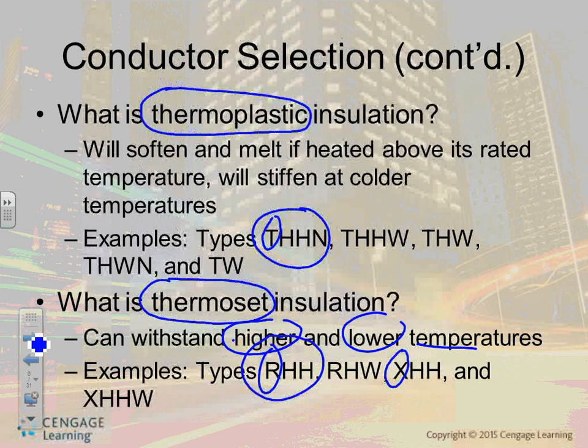What happens if you put the insulation in a very low temperature, 25 below, like Minnesota? The insulation will crack. Look at your skin in here when you're moving around. We age like crazy here, man, because of that weather. Don't you think so? Instead of having warm, nice weather, your skin keeps contracting and expanding in the winter. Imagine the conductor doing the same thing. So very low temperature, guys, is bad for the insulation because it damages the insulation and makes it crack. When the insulation cracks, then contamination gets into it, and eventually it will fail and short.